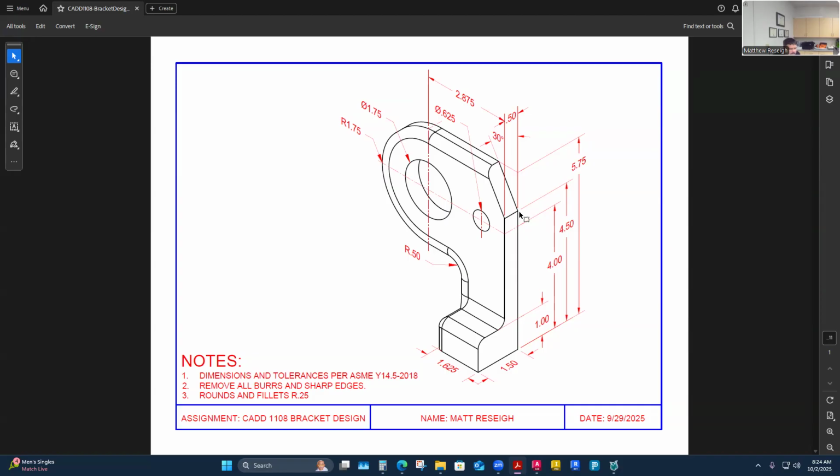across that, which is going to be my left side surface now. 4.5, and then 30 degrees down to where it hits. So I will use the degrees to establish that. And the 1 5/8, I'll take that all the way over to my circle. Maybe I'll put in a tangent line, and then I'll use a fillet to build this radius, I think.